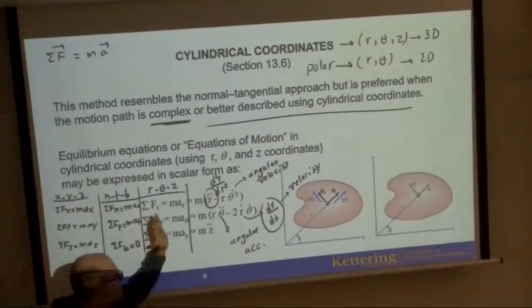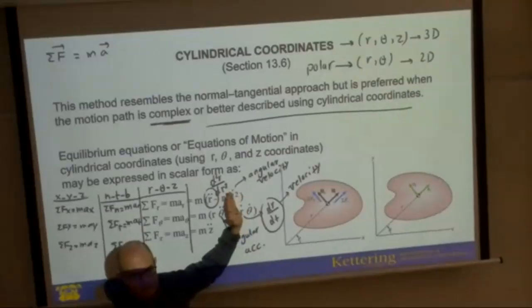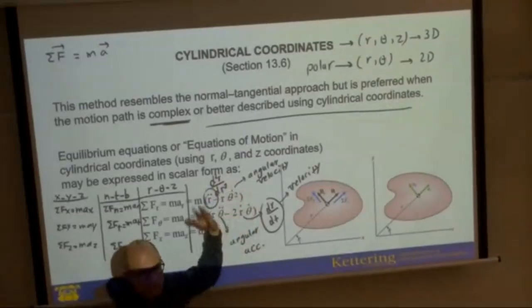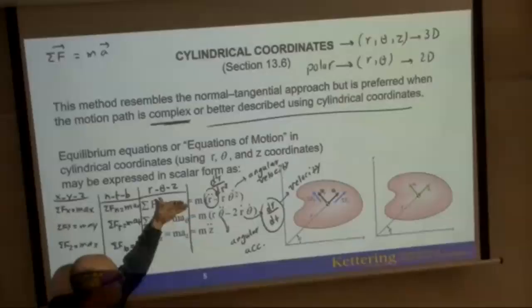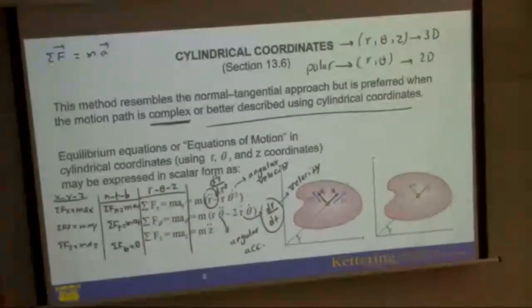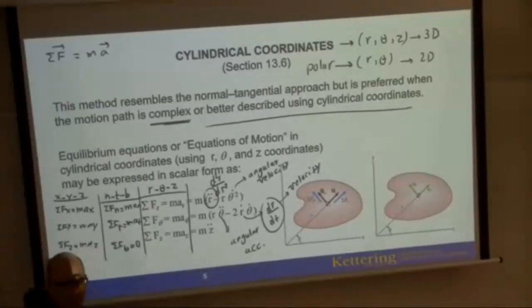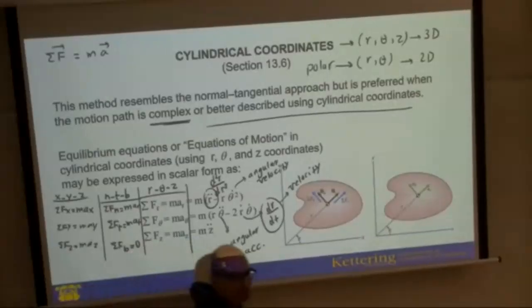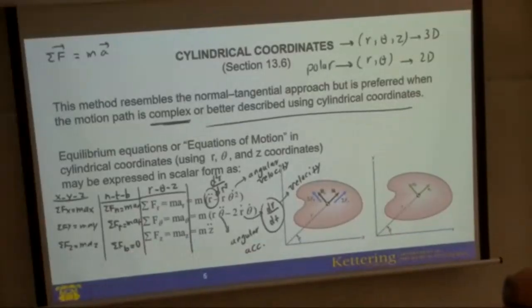The right-hand side of this equation is easy, it's just a mathematical calculation. You need to find the derivatives, or some of the values are given, such as angular velocity, angular acceleration, and r dot. When r is given to you, you can find the first or second derivative of r. In my opinion, this part is the easiest, because it only needs calculation and your mathematical knowledge. But the left-hand side needs a free body diagram. You know how to draw a free body diagram, but you do not know how to draw one for a curvilinear motion when you want to use the cylindrical coordinate system.